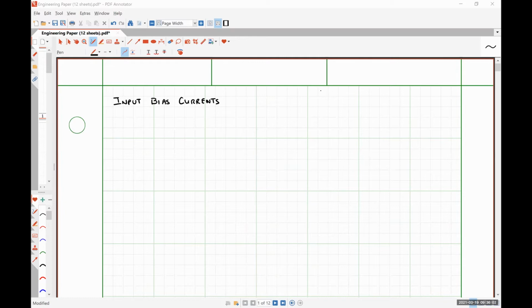Modern CMOS processes, the gate thickness is so small that literally rubbing your feet on a piece of carpet and then touching a pin is enough to completely fry a chip. And so they build in these little diodes on each of the bonding pads to prevent excessive currents from flowing in either direction, which protect everything. Typically, in a MOSFET-based amplifier chip, the values of these currents are on the order of picoamperes, so very, very small. Pico meaning 10 to the minus 12, okay?